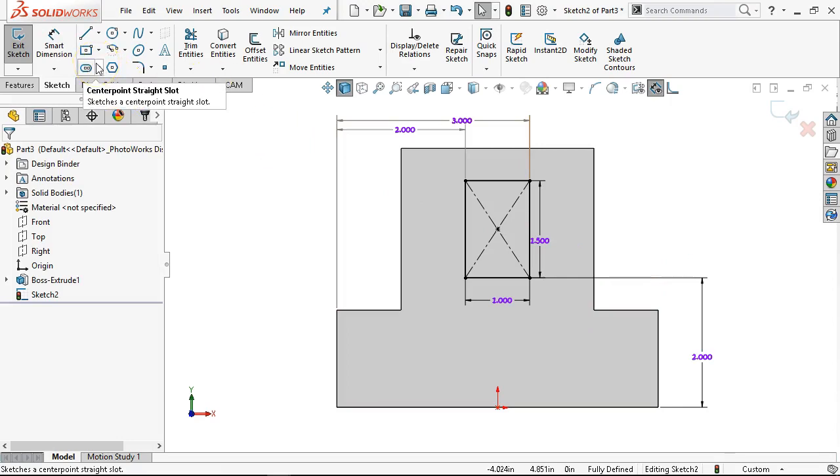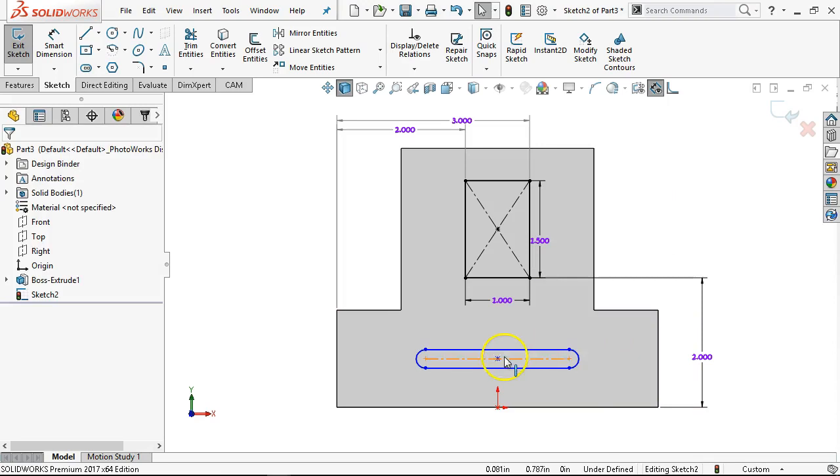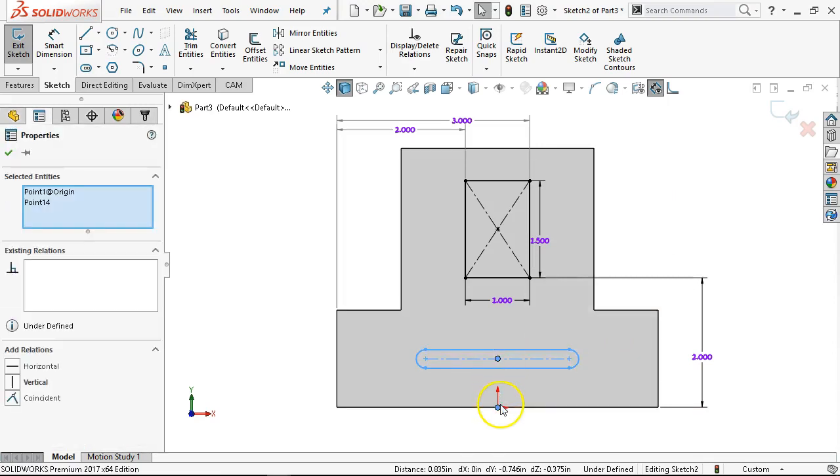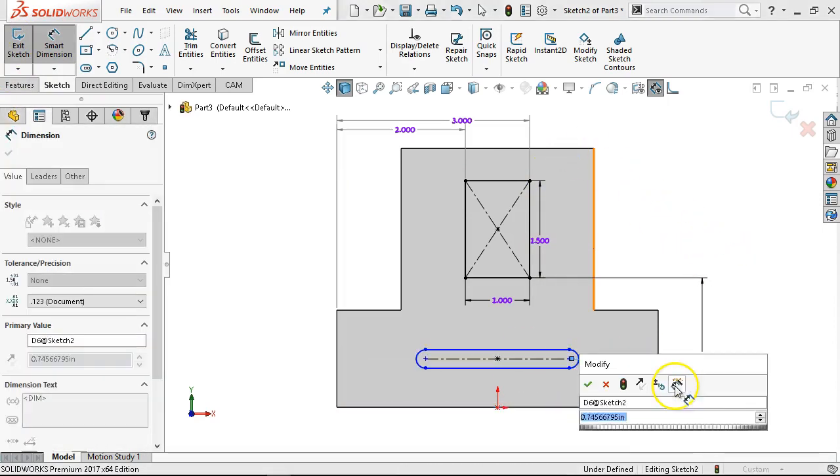All right, and then I didn't draw a center line on this, but we're going to go ahead with pretty close on the inference. So select, Control Select, and make the, did it apply? Yeah, so it applied. Make it vertical, and then we're 0.75 off of the base.